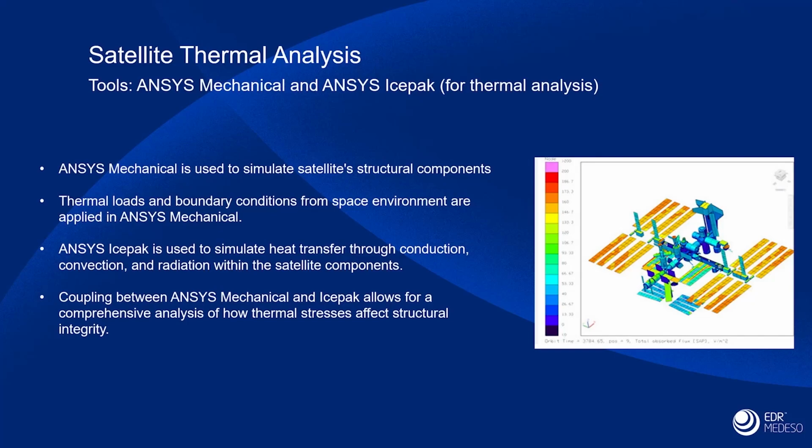Now, this touches on the coupling capabilities within the suite, and they're a massive focus within the Ansys environment. Icepak enables a heat transfer solution using a CFD method of the circuitry within the satellite components. And this then predicts the conduction, convection, and radiation. Those resulting thermal loads are fed back into Mechanical to provide thermal boundary conditions, and that enables the structural response to those thermal loads to be investigated.